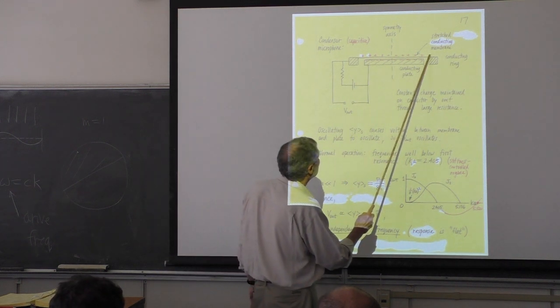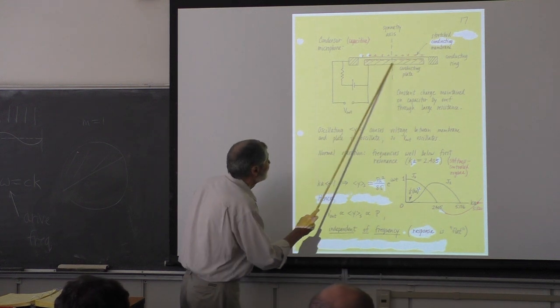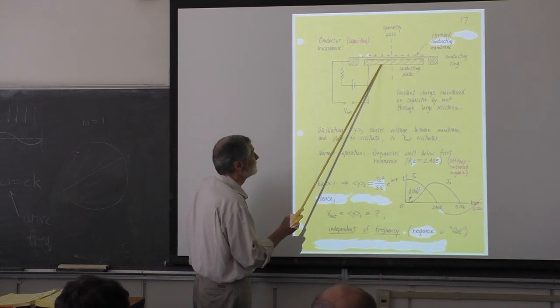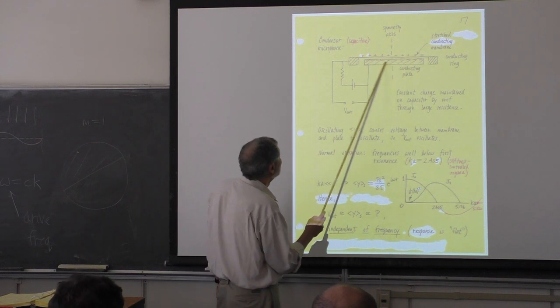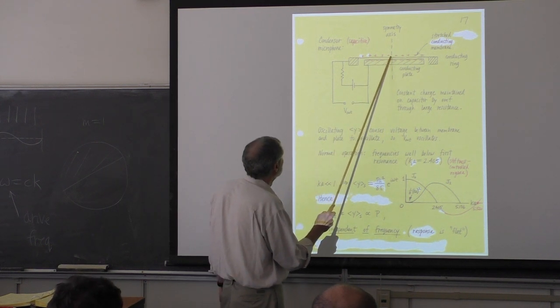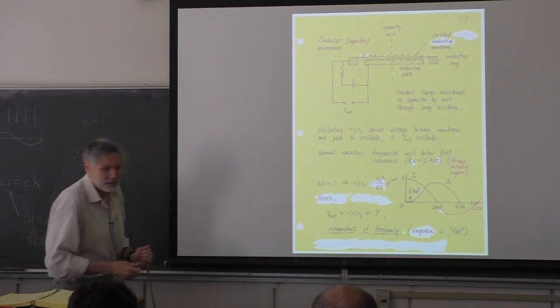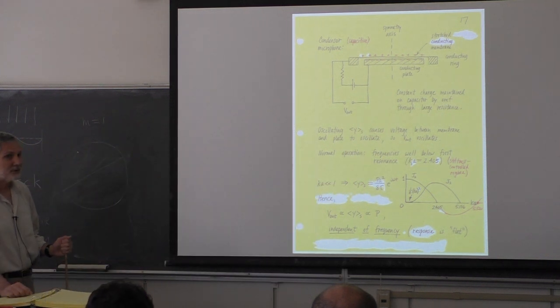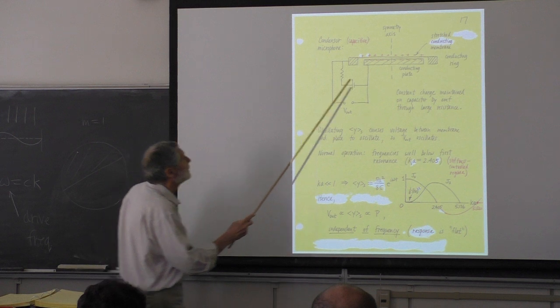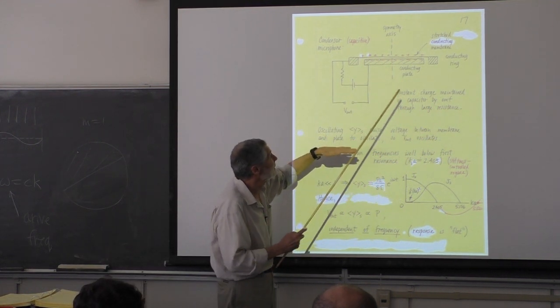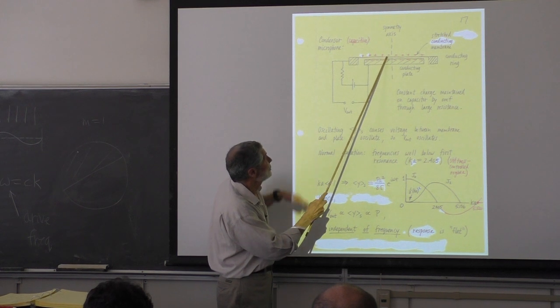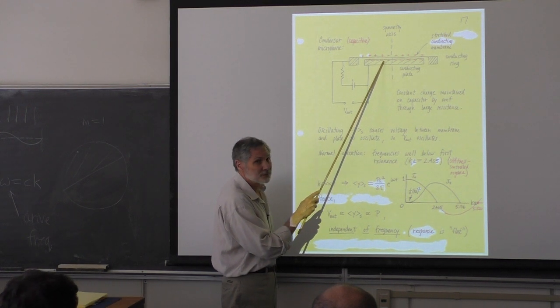That's the membrane here, and it's metallized. Here's the fixed conductor, the other plate of the capacitor. There's a gap here, right? And for this to work, of course, we have to have it charged up. So you charge this up, and when a sound wave comes here, it's going to move the membrane. For a fixed charge, the voltage will change here.